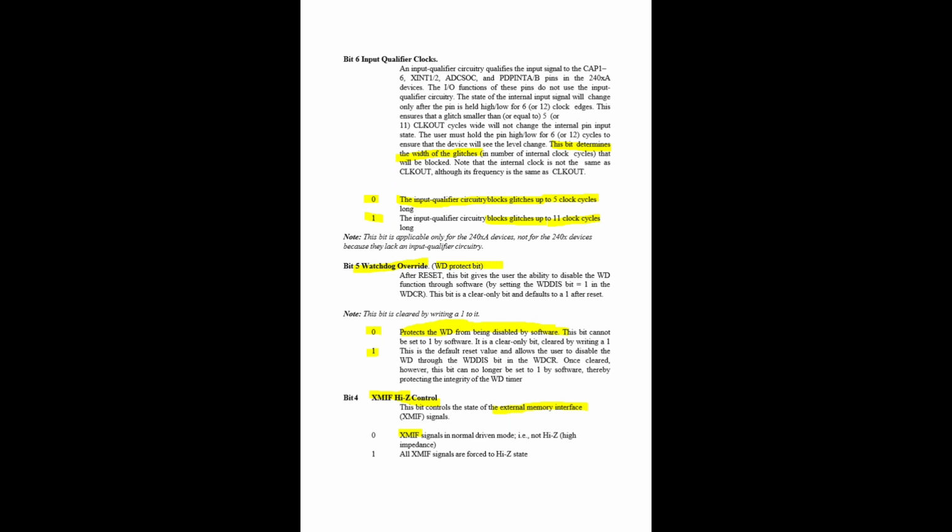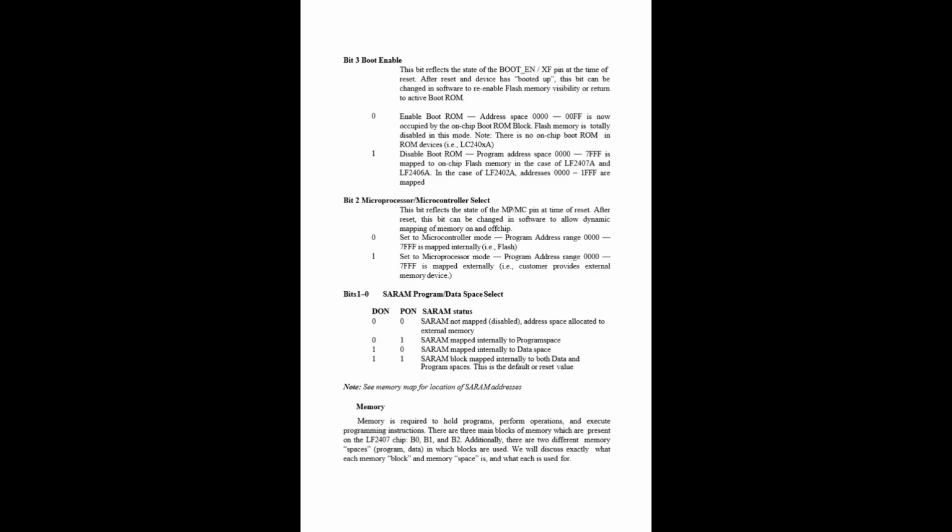So if it is 0, it is normal driven mode. That means you can transfer the data from external memory to DSP or DSP to external memory. That means not high impedance. If it is 1, forced to high impedance, you cannot transfer any data from the memory to the DSP or from the DSP to the memory.